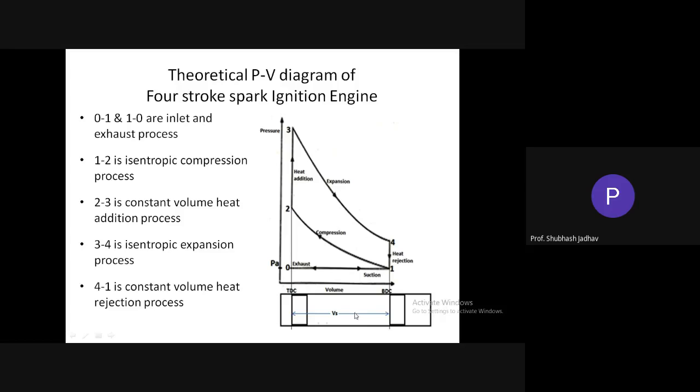So this was the swept volume denoted by PS. When the piston is moving up, what happens? The mixture that is trapped inside is getting compressed. That means the pressure is going to increase. So we can see over here, the pressure line cannot remain like this. When the piston is moving from BDC to TDC, the line has to move up.